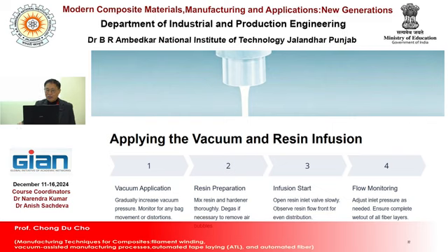And the resin preparation is to mix the resin and hardener thoroughly. The well mixed is needed. Okay? And degas if necessary to remove air bubbles. Okay? So the reason this kind of application cautions are listed, because in practice